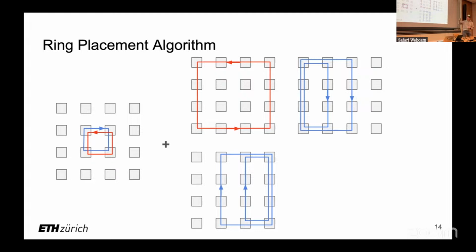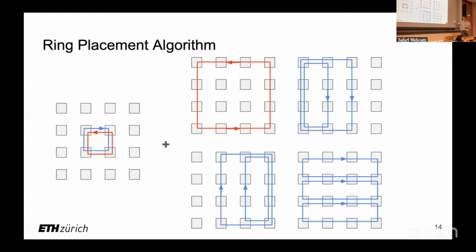But we're in a 4 by 4 design. So what they say is we want to have at maximum 4 loops simultaneously in one segment, and we haven't reached that yet. So what they do is they introduce a new set of loops. This is not to make the connectivity. The connectivity is already assured, but it's basically to better connect them up, to ensure more loops that you can route packets through, and to also maybe have lower hop counts, because you can choose your loop however you want.